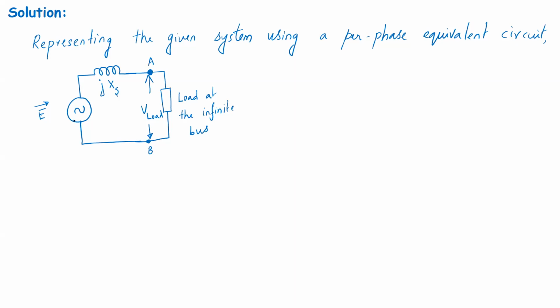The speed is fixed, determined by the frequency at which the voltage is generated as well as the number of poles the machine is built with. This is a 4-pole machine, and since we do not have the frequency information in this problem, we cannot determine the exact synchronous speed. Nevertheless, we can be certain that the speed at which the machine rotates will always remain constant.